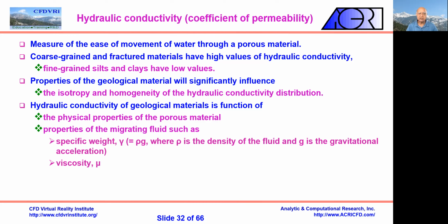That happens, okay. That's called anisotropy. Isotropy means, like a typical sand would be isotropic because pores are equally distributed, random, and water can go in any direction. But many rocks, for example, with fractures, you don't have isotropy. So this can happen. So hydraulic conductivity is a measure of that, okay.